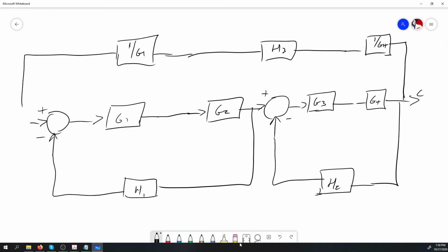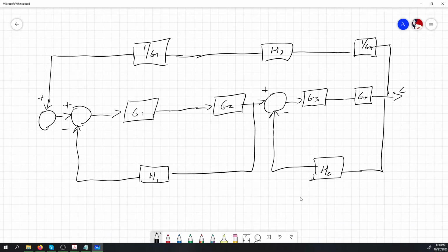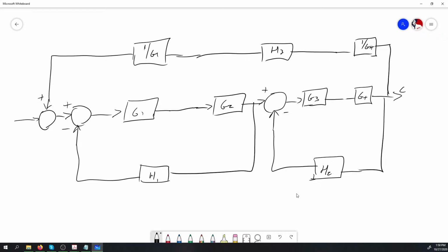And our new summation junction coming in here, R, there, nice. So in one swift move, we basically moved our takeoff point and our summation junctions to the outside, or the extreme edges, of the block diagram. And we just made sure that we compensated accordingly for when we moved them, to obtain our compensation blocks in particular.